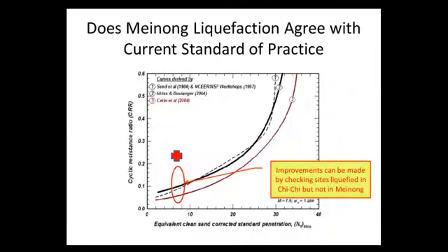This is the part that says there are a lot of areas that did not liquefy, either from the Chi-Chi earthquake or from the Jiaquan earthquake. This is because the PGA, the peak ground acceleration, is low. But since we have the material property, we can probably calibrate the liquefaction curves near the lower end.